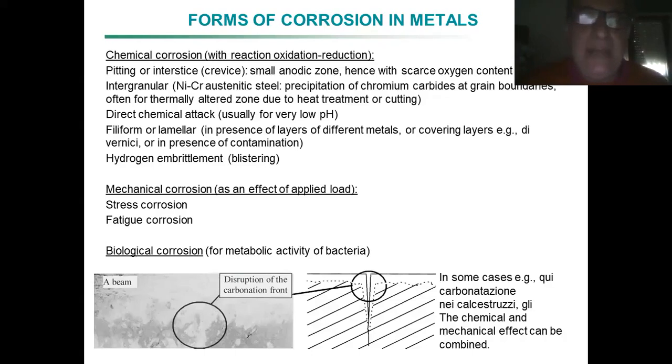And of course, you can measure that in corrosion studies, as I'm showing later on in this lecture. We can measure the potential to show which metal is more prone to corrosion than the other; it's more anodic. If these two metals constitute the two electrodes, the one more prone to oxidation would go to the anode, and the other would constitute the cathode.